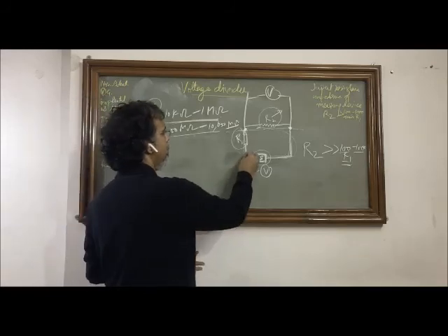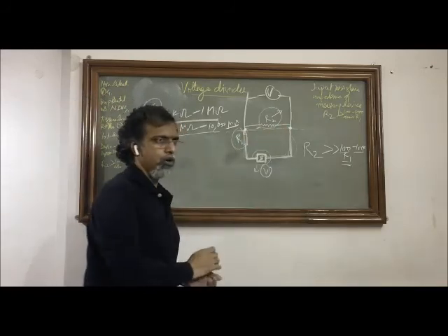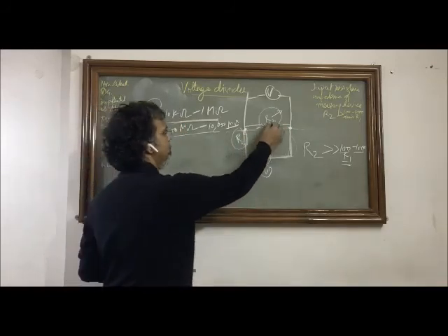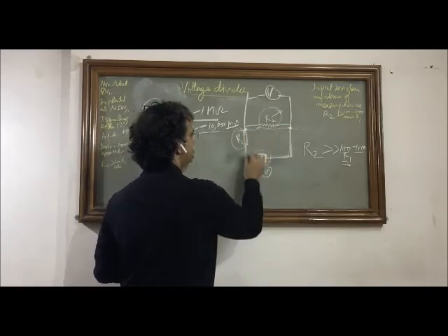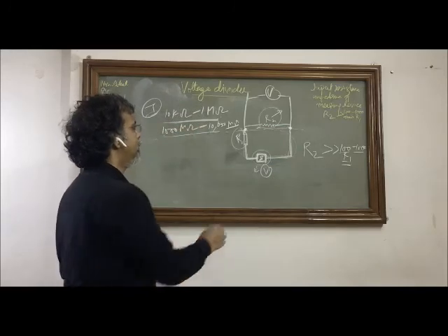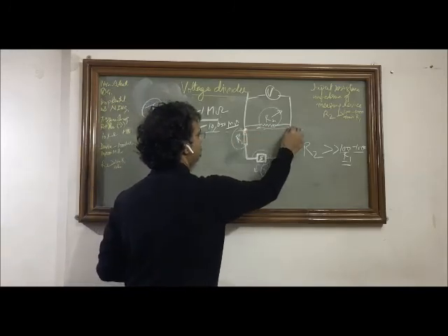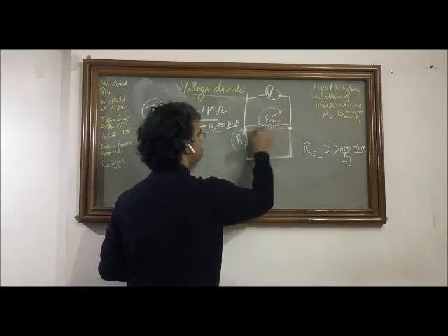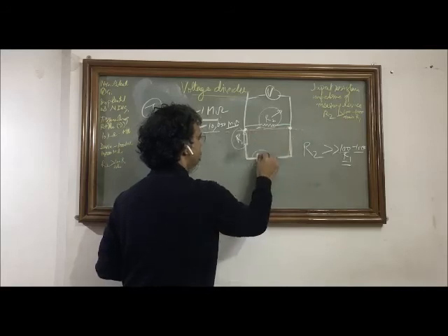Now here we wanted very little potential drop at R1, so we made R2 so high that practically no energy is lost, and we are assuming that the potential picked up by our measuring device at the skin surface is almost equivalent to the potential difference generated by this biopotential generator or some tissue.